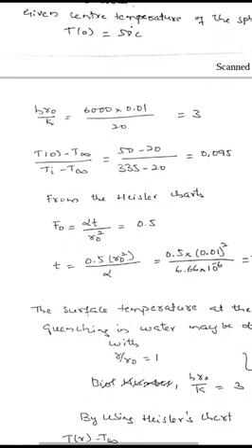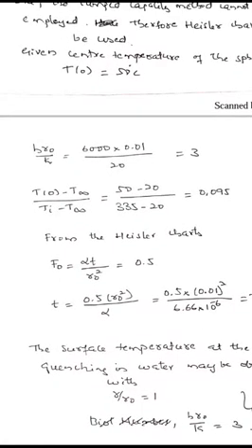Note that here we have calculated h R0 by k just for referring to the chart, not h R0 by 3k. You have to refer to the chart according to the parameters given in the chart and calculate the values accordingly. If the data handbook gives h R0 by k, calculate h R0 by k only and refer to the charts.